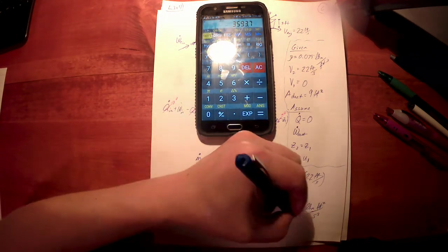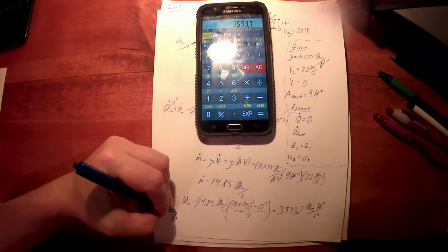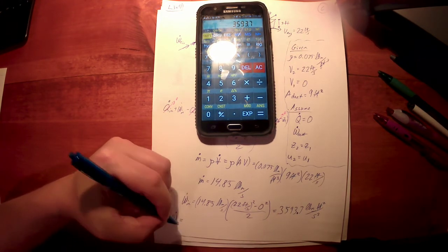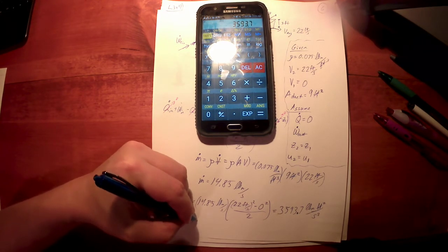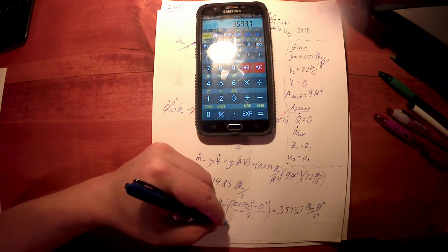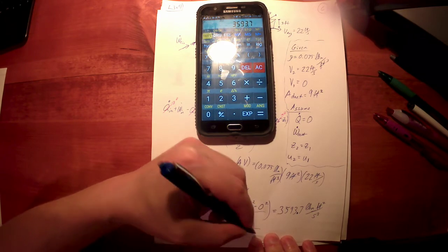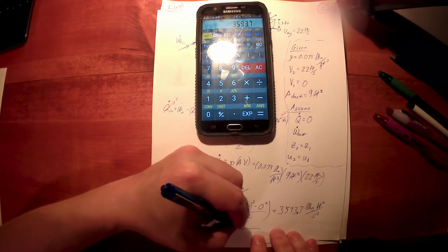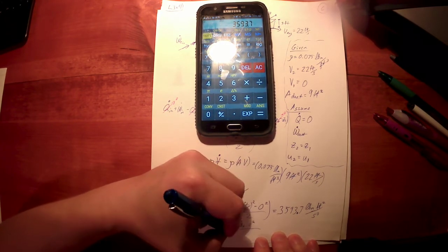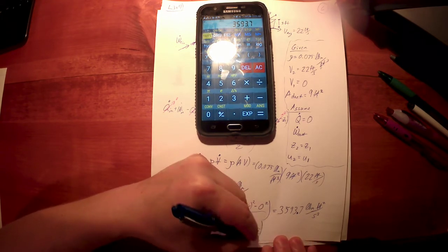All right? So what do I do with that? Well, that's not power. What units would we like? I'd like watts or I'd like horsepower. So how do I get there? There's a couple things I can do. 3593.7 pound mass, feet squared, per seconds cubed. Remember the first day, I said there's this conversion factor. I could say 1 pound force, second squared, for every 32.2 pound mass feet. That is a conversion factor.